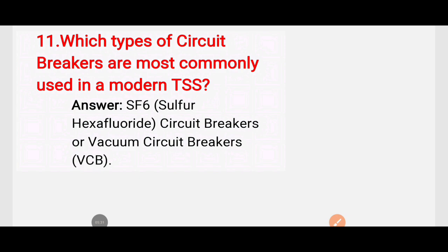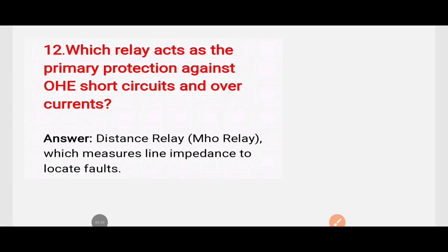Next, which relay acts as the primary protection against OHE short circuit and overcurrent? For detecting OHE short circuits and overcurrents, distance relay is used. Distance relay measures line impedance to locate faults.